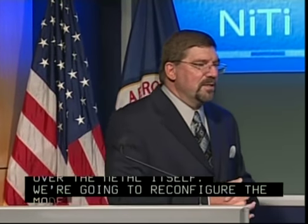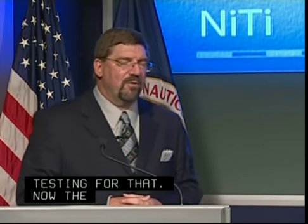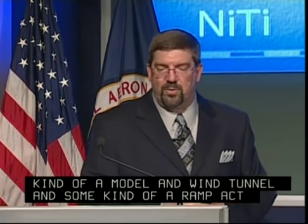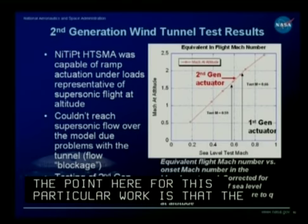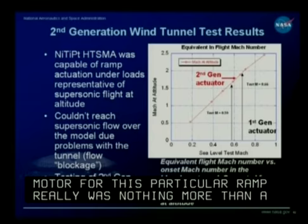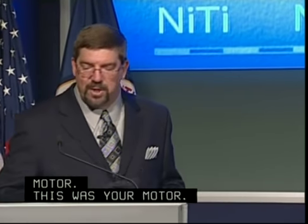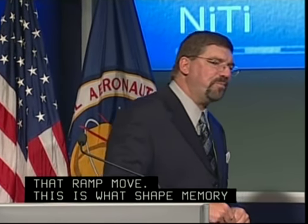Now the thing is that it's not unique to have some kind of a model in a wind tunnel and some kind of a ramp actuating or moving. The point here for this particular work is that the motor for this particular ramp really was nothing more than a piece of wire. So this is not wire hooked to a motor. This was your motor. This was the wire used to make that ramp move. This is what shape memory alloys are used for. So if we go to the next slide.